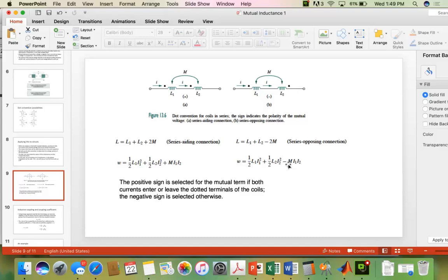And so if you have power distributed across a long geographical region, then any inductive kind of filter that you would put at the end of that long transmission line, it would not couple all of the flux. So you wouldn't have the effect then of that inductor canceling out the inductance of the power transmission line. So that won't work for that circumstance.